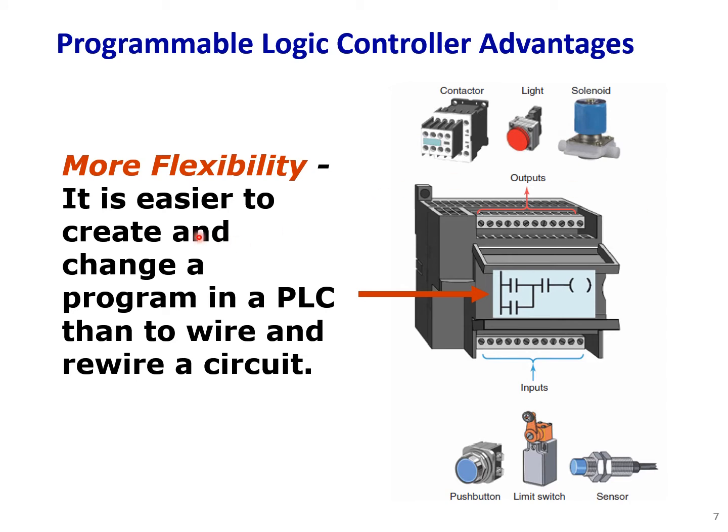The next advantage is more flexibility. It is easier to create and change a program in a PLC than to wire and rewire a circuit. This is one example of a ladder logic PLC program.